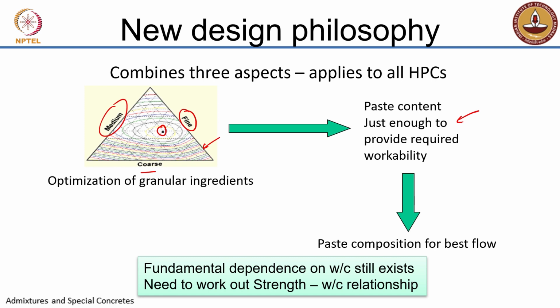Shrinkage. I don't get dimensional stability. Aggregates are absolutely essential for dimensional stability, right? You need more aggregate to have more dimensionally stable concrete. And the aggregate phase, as compared to the paste phase, is going to be inert in most circumstances. So you'll get better durability if you have good aggregate combinations. But one more important aspect. Why do we want to maximize aggregate? Which is a very practical aspect.